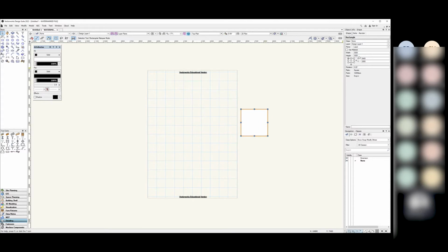And it does get a bit more complex than that. There's this little bit just underneath. So for instance, we're currently making this rectangle. And you see I've got a little dot on the top left corner of the rectangle, yeah? So this essentially acts as like a base point. For those of you that are familiar with AutoCAD, you'll know what I'm talking about with base points. But if not, don't worry. Essentially, it's just saying that any changes I make are going to be in relation to this top left point, because that's the point I have selected.